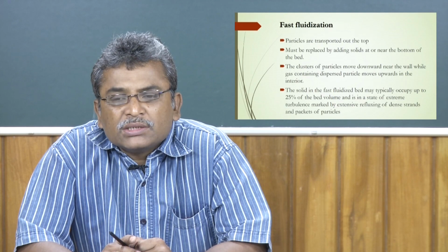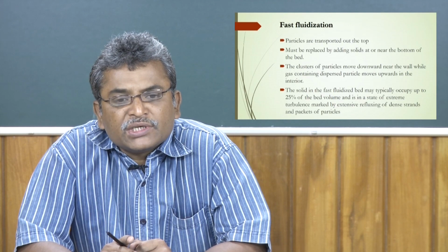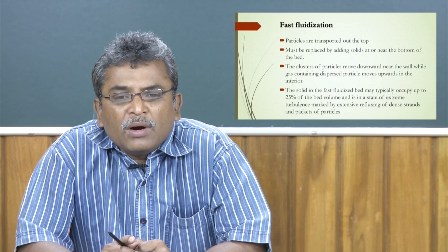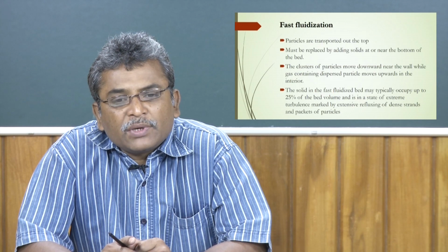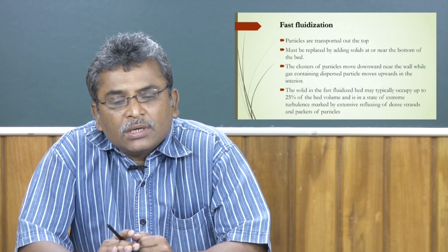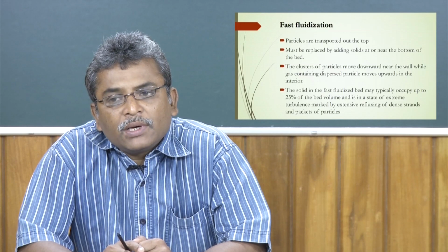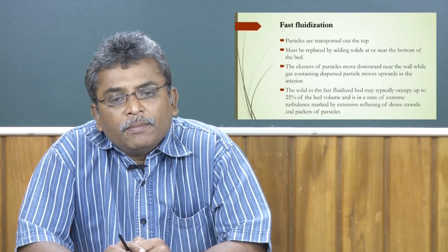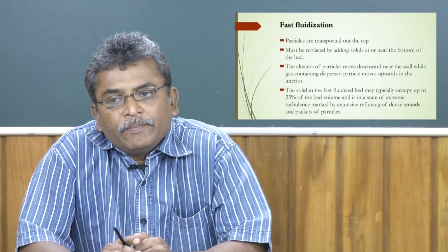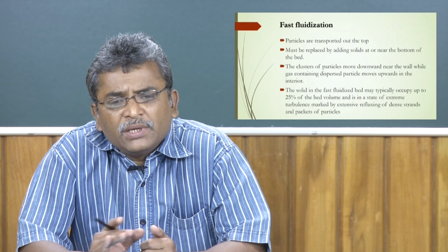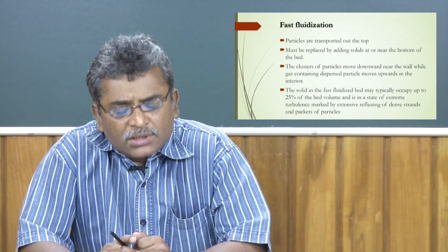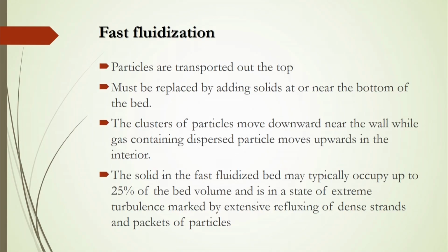So, at 20 times the terminal velocity, you will see particles will not be coming back to their original position, and they will move up and be transported out the top. That transported solid will be separated from the gas mixture by some separator, and after that it will be used again for this fluidization. So, in this case particles are transported by the gas here.